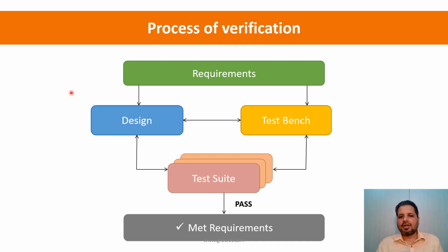As we saw in the previous slide, our digital IC tester was able to apply the different inputs, right? So similarly, the test bench will hold the design, and it will provide a mechanism through which we can apply different possible inputs to this design. And the capabilities of this test bench are used by the test suite.